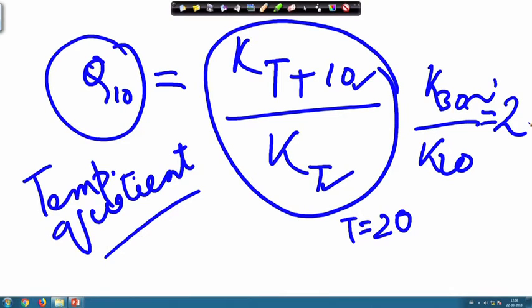Right. So any rate of reaction, be it chemical, microbial, biochemical or enzymatic, any kind of reaction will follow this simple temperature quotient law: a reaction at a temperature, say 20 degree, if the temperature is raised by 10 degree, so that is 30 degree, then the rate of reaction which was at 20 degree will now become double at 30 degree than that at 20 degree.